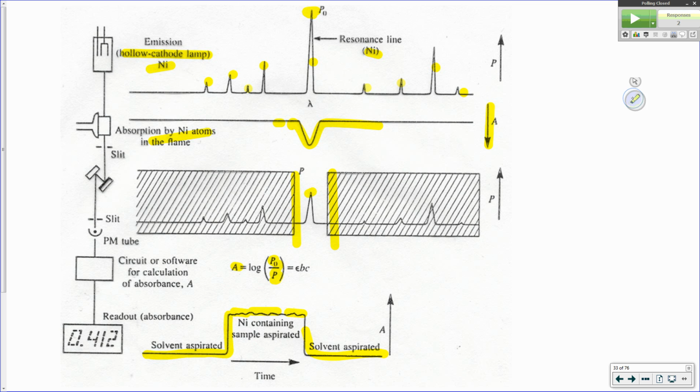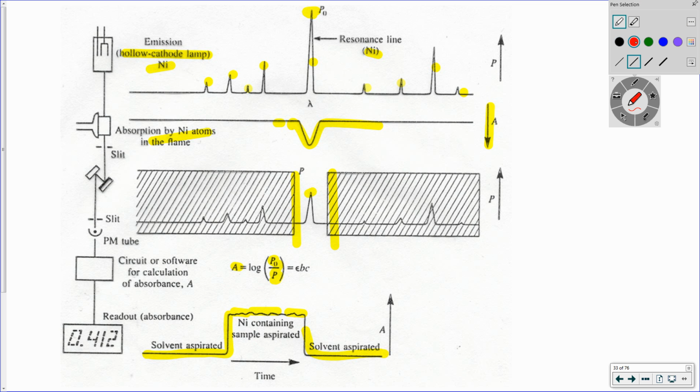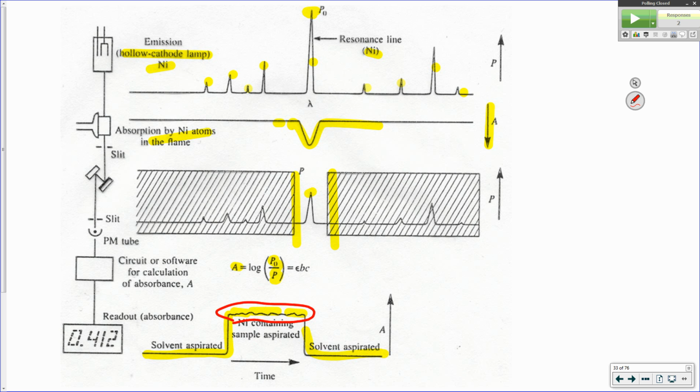And this thing down at the bottom, that being static and moving, not a straight line. A flame's not something that's solid state or steady state. I mean, it's moving around. So what we end up doing is we integrate over a long period of time and get an average. So we'll average a signal anywhere from maybe 2 to 10 seconds and take that average signal.